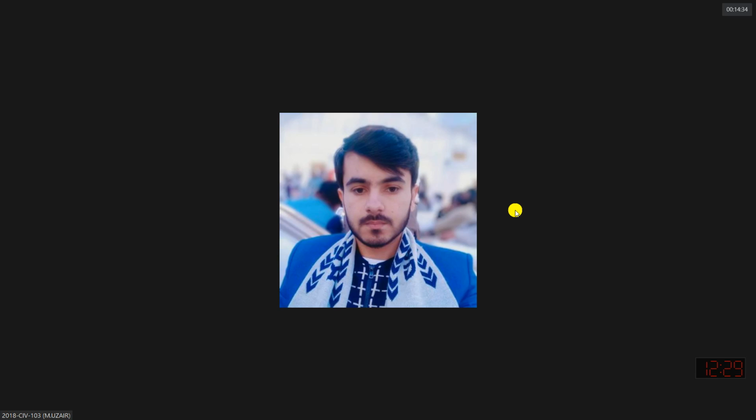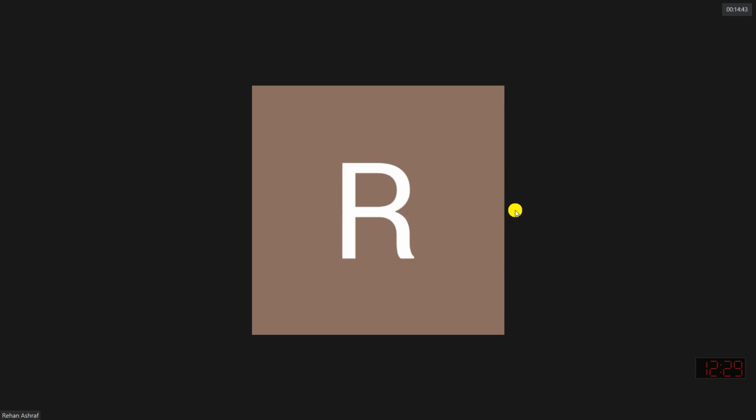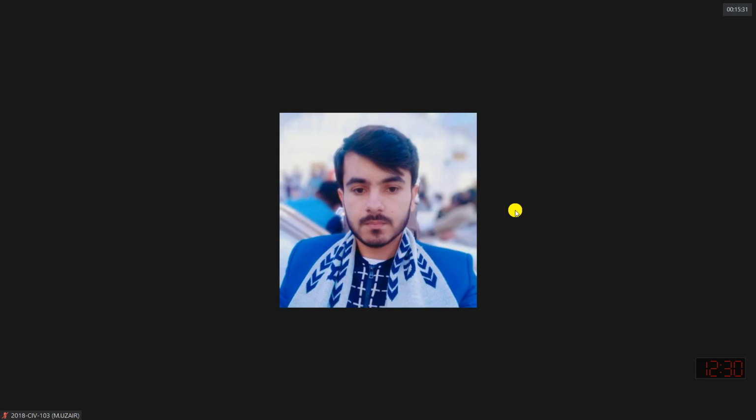सर इस तरह से हो सकता है यहाँ दो वॉल्स हैं, उनमें जो डिफरेंस है वो 2-3 फीट का, लेकिन हमने स्लैब तो ओवरऑल ऊपर प्रोवाइड करनी है, मतलब अंदर वॉल है ही नहीं। वो आपको देखें, स्लैब की पेरिफेरी आपको क्लोज करनी है, ठीक है? तो वो आपको बीम से क्लोज करनी है। अब उज़ैर मैं आपको बताता हूँ, वहाँ पे 2 or 3 फीट स्पैन इज नथिंग। इवन अगर आपका स्पैन 3 फीट तक भी है, तो व्हाट यू कैन डू इज यू कैन प्रोवाइड 2 or 3 नंबर 6 बार्स, या 2 बार्स नंबर 6 के प्रोवाइड कर दें वहाँ पे स्लैब की रीइंफोर्समेंट के साथ ही, तो दे वुड एक्ट एज अ बीम, ठीक है? लेकिन यस पेरिफेरी आपको क्लोज करनी पड़ेगी स्लैब की। मतलब अगर मैं स्ट्रेट इसका आंसर दूं तो बीम प्रोवाइड करना पड़ेगा।